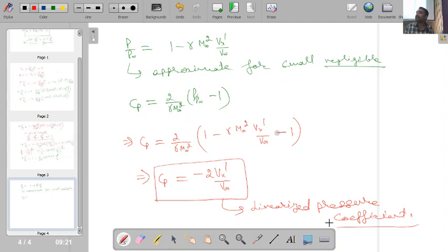Why are we saying linearized pressure coefficient? Because we have applied over here the small perturbation theory. Okay, so once we have applied small perturbation theory, that theory gives us for a typical flow situation the linear form of the velocity potential equation. So that's why from that Vx dash component only we are able to find out the value of Cp. So we are calling it the linearized pressure coefficient. Is this point clear?